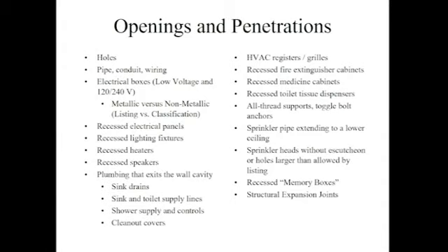So we typically either do what we call a box over the top of it, which is really a recessed ceiling, or it's a popped up little ceiling, just like the kind of stuff we do for light coves and pop-ups in a corridor, but it's much smaller. You pop it, and so you basically take that roof ceiling assembly membrane up and over the top of the speaker, and then the hole that's cut down below is essentially an unrated little section of that ceiling.